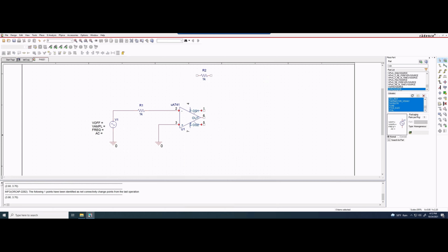Now in the lab, we have to measure these resistances actually in person, in real life. We have to measure them with a digital multimeter, and so our values are going to differ. It's not going to be exactly 1K, that's the exact value. We want the experimental value, not the theoretical value. So in here we're going to type 0.993, press enter. That's for our R1, and then this is for our R2. Again, I measured these values, so they can be a little bit different, but it should be close to 1,000 ohms. So that's what we're going to have here.